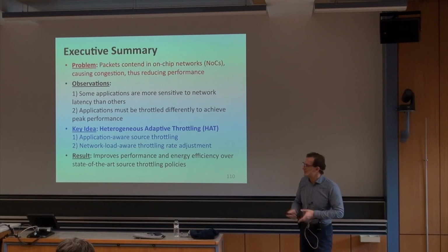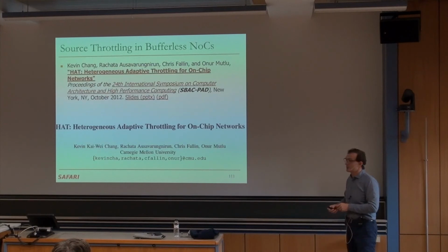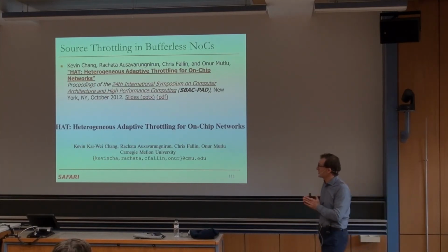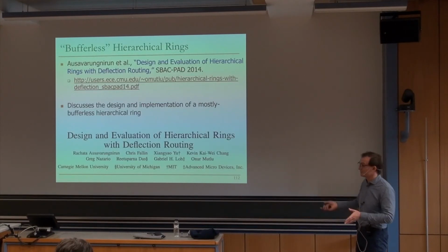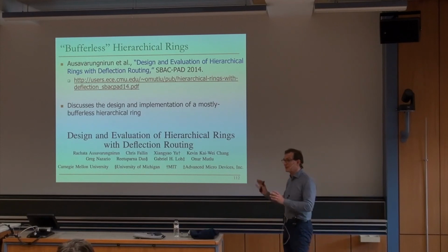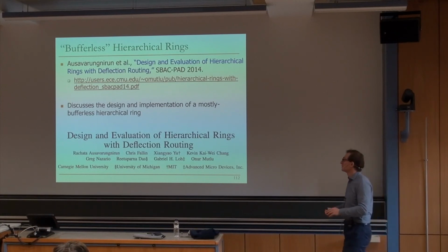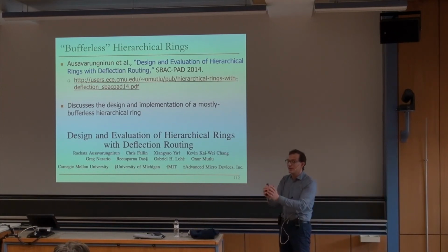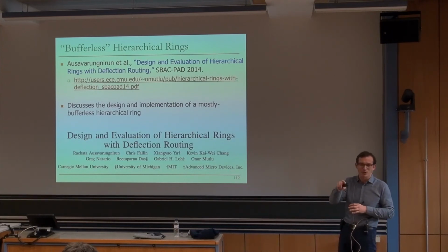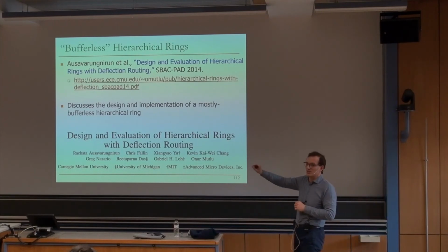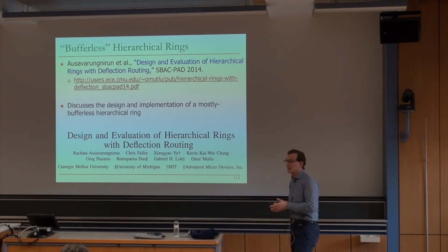Make sense? And that's one idea. Again, I don't go into detail. If you're interested, you can read this paper in more detail. So there's a lot to be talked about bufferless networks, actually. We didn't even talk about application of this to different topologies, but deflection routing is a very general idea. It's actually a very good idea in rings, for example. If you have hierarchical rings that we discussed yesterday, it makes a lot of sense to do deflection routing in rings, especially if you have small rings and hierarchy of small rings. Deflection doesn't cost that much. You basically circle around the small ring again, and then hopefully you get to your destination ring. Hopefully the next time you try, you're not deflected, right?